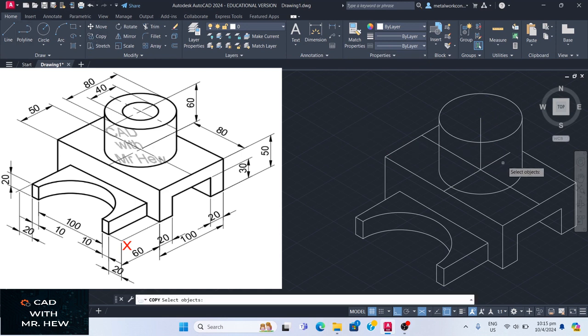So I'm going to copy the center lines, this and this. Enter. This is the base point. Come up here now. Enter. Right? So let us draw the R now. So go arc, isocircle. The center would be here. The diameter. So let's click the diameter just to make sure it's 40. Enter 40. It says start angle. So we're gonna go there, there, enter.